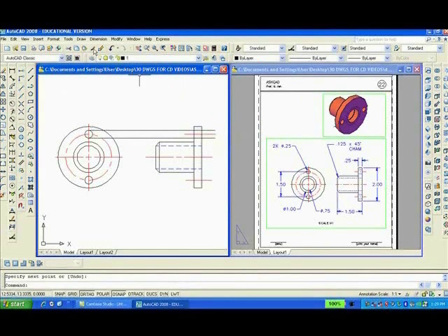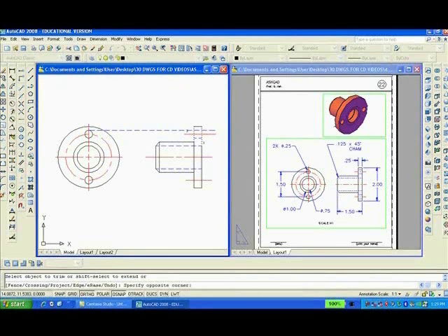And using Match Properties, take that hidden line and brush those. And then I can trim, TR, enter. I can trim from that line and that line, enter, all these excesses. I could even copy from there to there.